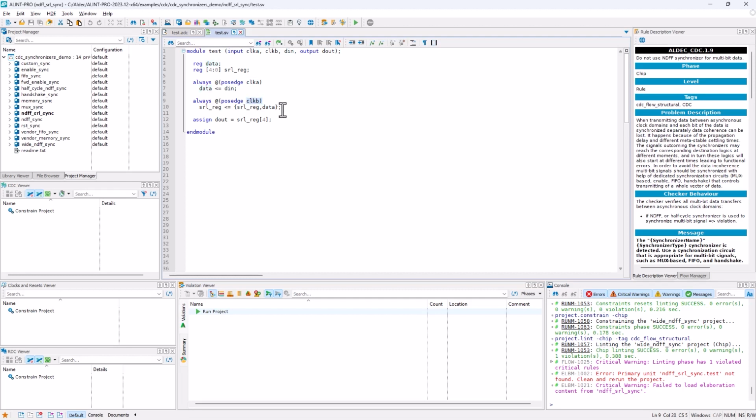But instead of just being fed through two chained D flip-flops, we have this setup here where we have what looks to be a shift register, because we have the data being at the bottommost position, and then all of the bottommost bits of the shift register being shifted over 1 into the topmost bits of the shift register. However, the shift register is just a bunch of sequential or in series or chained D flip-flops. And then finally, the topmost bit of the output of that shift register is our output here.